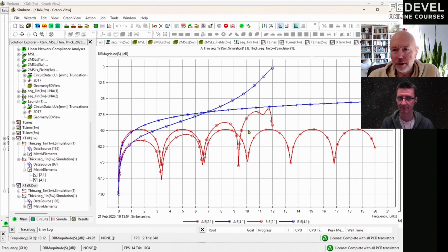Now those requirements are revised because crosstalk is back, because you need more tracks, higher density, and minus 40 dB is okay. It depends on the expected attenuation of the signal. So if you expect signal attenuation at minus 40 dB, then crosstalk requirements may go up to minus 70 dB. But if you expect only like minus 20 dB, in this case, minus 40 dB, minus 30 dB, it all depends.